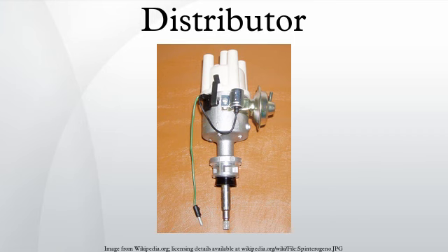Oil, dirt or other contaminants can cause similar problems, so the distributor should be kept clean inside and outside to ensure reliable operation. Some engines include a rubber O-ring or gasket between the distributor base and cap to help prevent this problem. This gasket should not be discarded when replacing the cap.